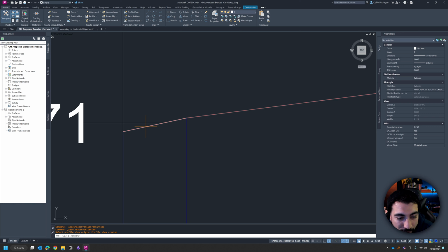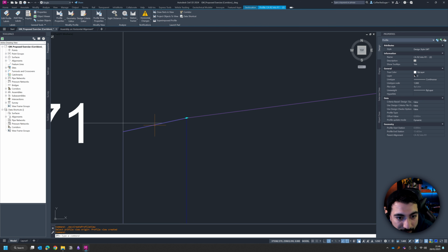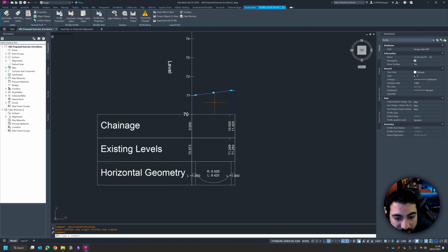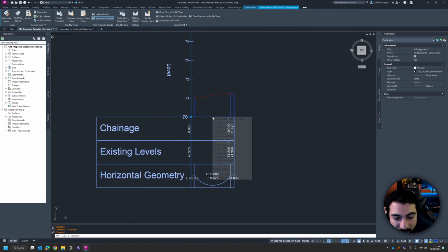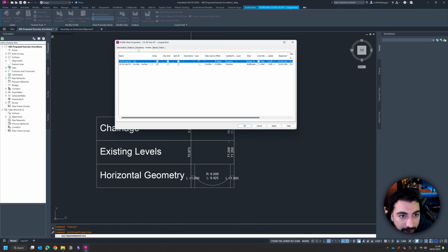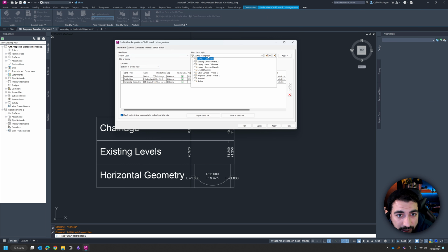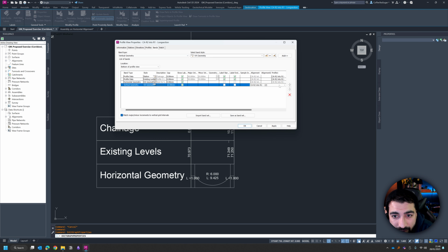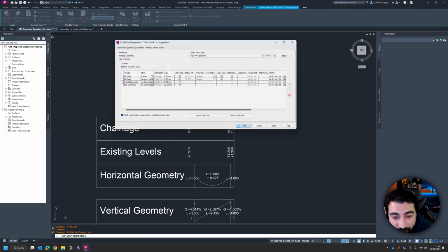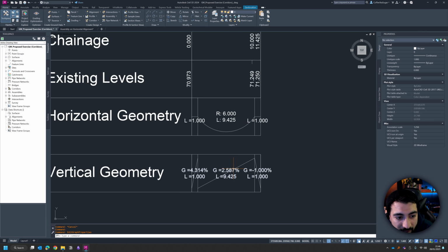So you can see you've got the first bit of the road and then the other bit, and then it tried to keep it at a crossfall of 6, I believe. So let's see if we can add the band, because the band was missing. What band do I need? A vertical. We can add it. First time I'm adding the band, so it did 2.5% apparently.